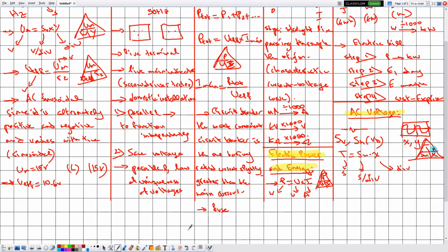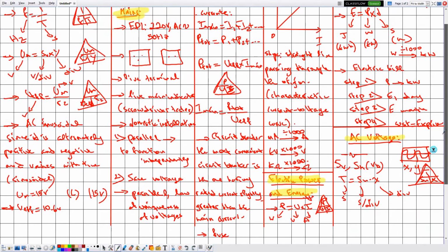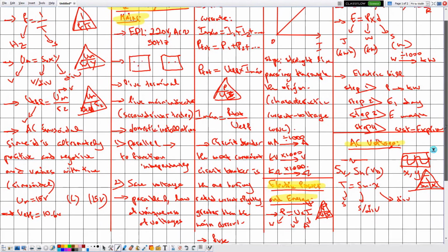It cannot be switched on again, and the voltage of the fuse is 0 because it is of negligible resistance. What is the difference between the fuse and the resistor? The resistor is used to let other components function normally, whereas the fuse is installed in order to protect the circuit from overload and current.